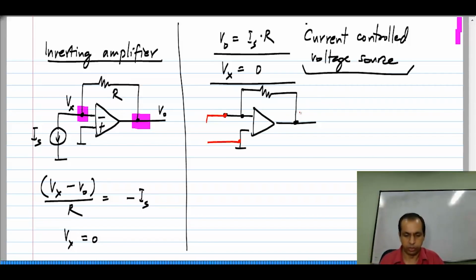So, you can only use a test current. So, I can apply I test and see what the voltage is between these two nodes, and I already have the solution to that. This circuit is exactly the same as that one.